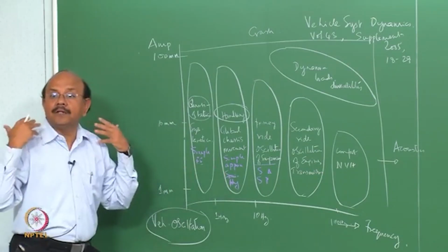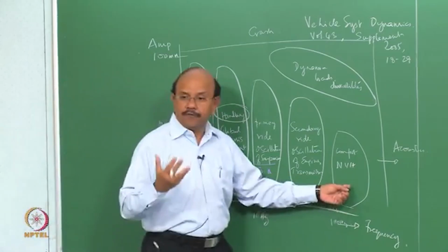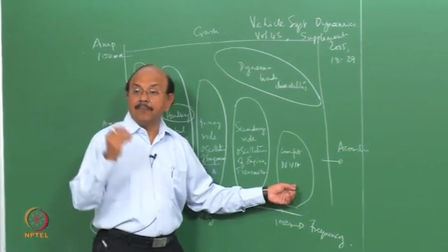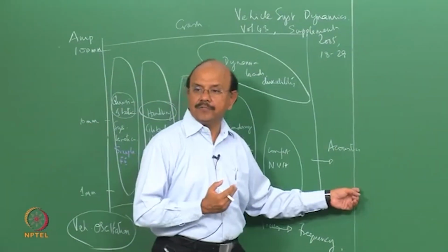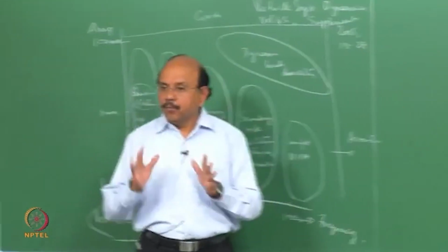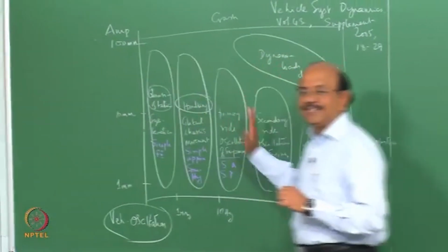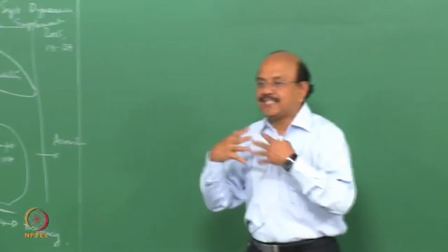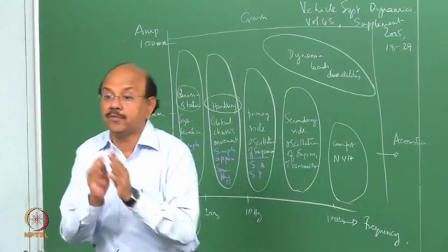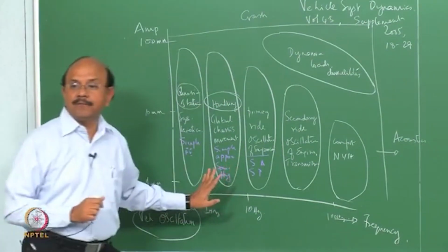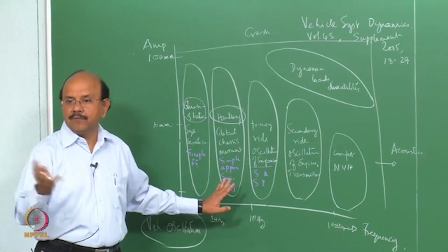But at the same time, if I am looking at the NVH, the vibration characteristics and comfort, for example, I would look at these frequencies. If I am looking at acoustics, I would look at higher frequencies. The vehicle is moving, and you are artificially distributing it at these frequencies and studying the effect at these frequencies. When I say go and study at this range, it means that you are looking at handling, and that's the result of the characteristics of the vehicle when it takes a corner.